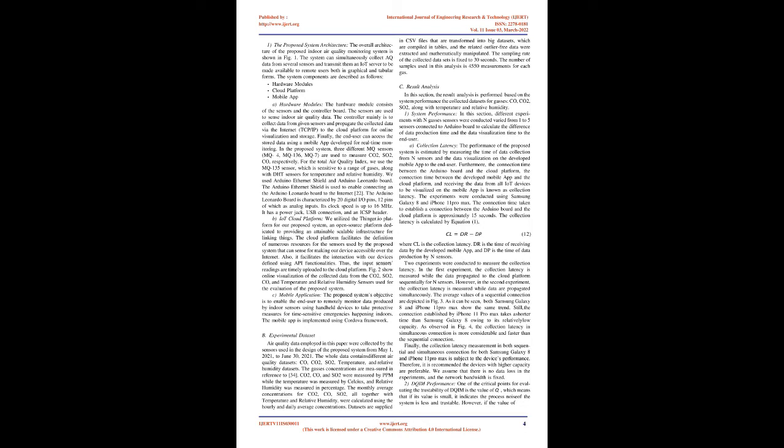DQIM is proposed to improve the quality of data collected by low-cost sensors. It is based on the KF, which is mathematically described in Equation 1. Equation 1 describes the implementation of the proposed system, where xt represents the signal value, which is a combination of its prior value xt-1, a control signal ut, and a process noise weight wt. ut is the control signal, which is a particular external factor affecting the system.